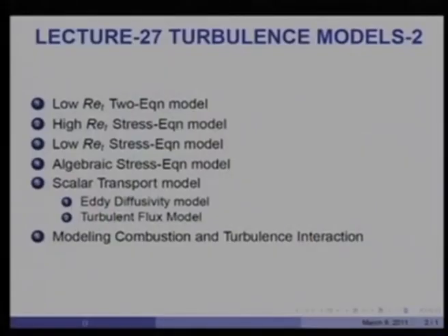I would first describe the low turbulence Reynolds number two equation model, where the turbulent viscosity is calculated from kinetic energy and dissipation equations. But then the other approach, as I said, is not the eddy viscosity model, but to actually solve the differential equation for Reynolds stresses.